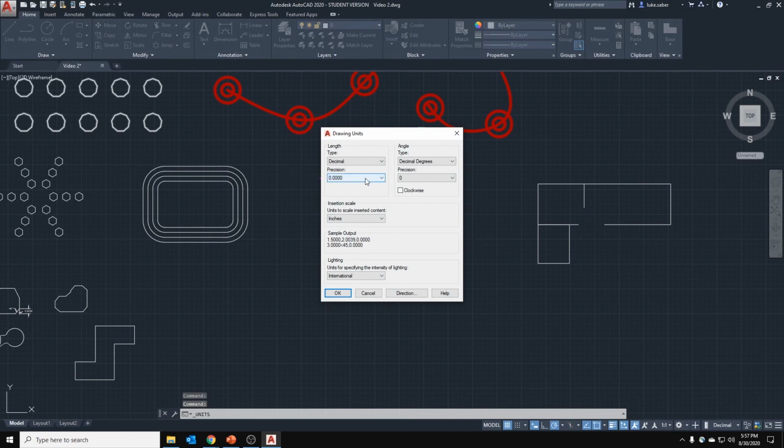You can also check what you want to do for an angle. So you can do radians, g-radians, surveyor units, degrees, minutes, seconds. And the last thing for this is precision, which means once you do it, if you put in maybe 6, it will follow by a bunch of zeros. If you do 6.75, and you had 3 or 4 zeros, let's say 4, it'll have an extra 0. 6.750. It'll show you all of those.